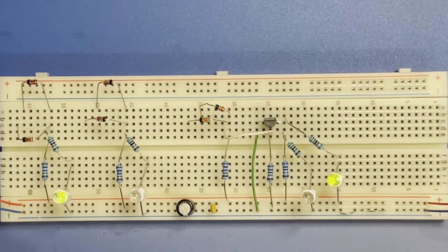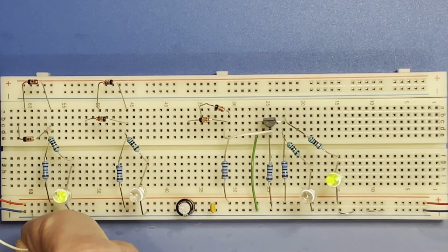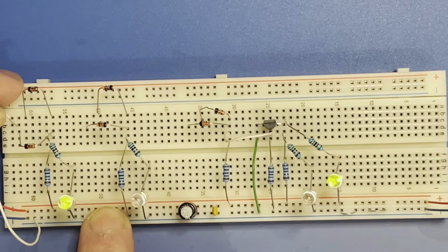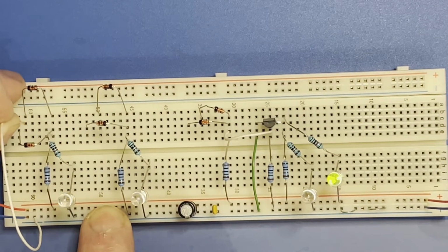And if I ground either of the inputs so they're not both at one level, there. I'll look at the camera to make sure I'm doing it right and look at the strip board at the same time, which is difficult. Grounding either of the inputs turns the diode off. So in a truth table sense, that is an AND gate. And to a limited extent, that will work as a real-world circuit.